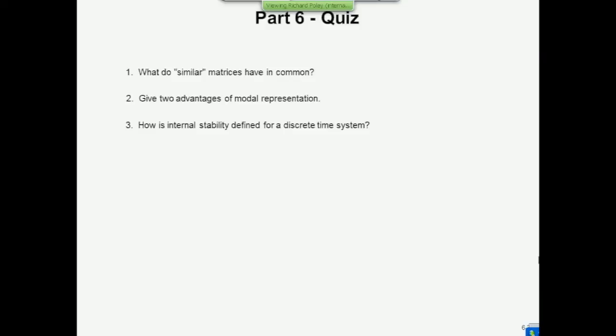How about internal stability for a discrete time system? Yeah, that's steady state. You're right, that's steady state. So internal stability, we call that another name, and Vishal knows it was bounded input, bounded state. So as long as the input's bounded, is the state bounded? If so, it has bounded input, bounded state, or internal stability. But what about this discrete time thing? What are we saying about the system if it has internal stability? I mean, the internal stability is a bit of a red herring, really.